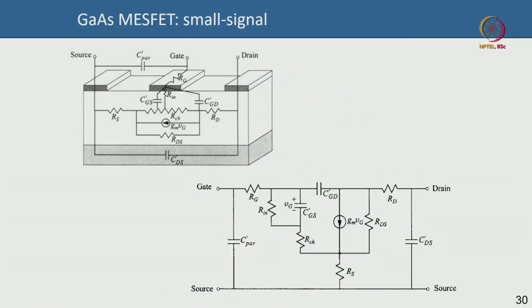So, this was the last slide in lecture 18, where we were talking about the small signal model, different components, resistances and capacitances in this small signal model. Inductances are not shown here because inductances become more relevant when you have bigger devices. Why I say that is that any metal line tends to become an inductor at sufficiently large length, and you need these wires, long wires or long pads or long metal bars.